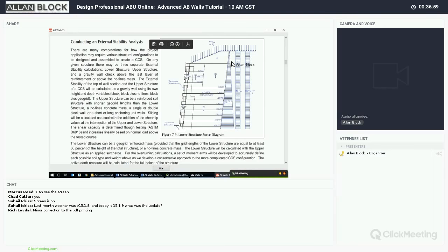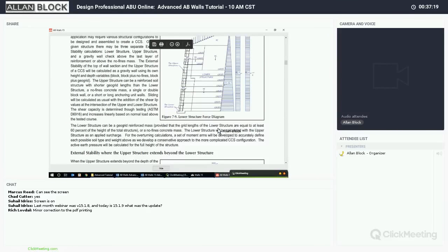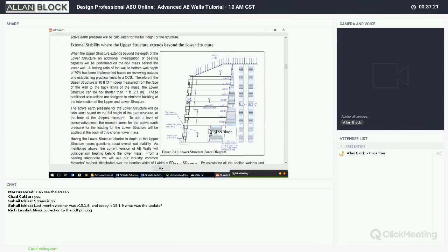Right? So we know that if we're looking at the entire wall height, this is what we're looking at for the lateral pressures, the dynamic loads, the surcharges. We've already shown how the top of wall is going to be modeled. The bottom of that uses the total height of that wall. So it's not like we're just looking at this height. We're taking the entire height of that mass and applying it. So it's relative, and it's accurate. It's not individual. We're looking at it still as one mass structure.